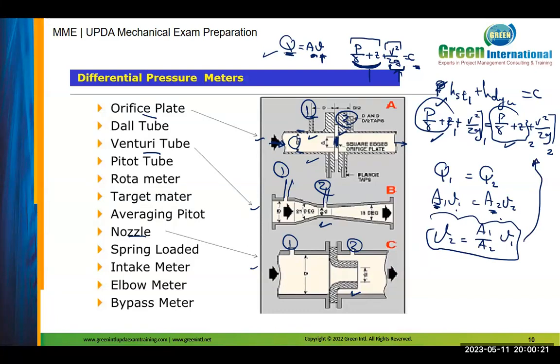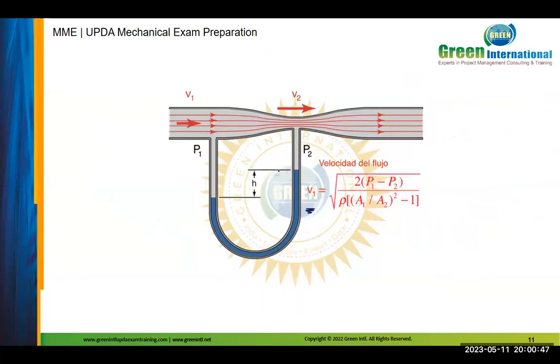If you don't understand what P1, P2, and the area refer to, or what rho is, rho for what, rho for the manometer or rho for the flow, which rho? It is important to understand what each term refers to. For example, this is rho for the equation itself, which is rho for flow. Delta P, P1 minus P2, I can't get directly. I can get the difference between the two pressures, which is h. So this reflects gamma h. Which gamma? The same as for the flow? No, this is gamma for the manometer. This is the little note you should be aware of.